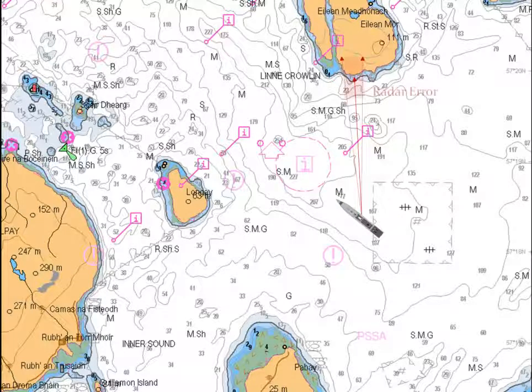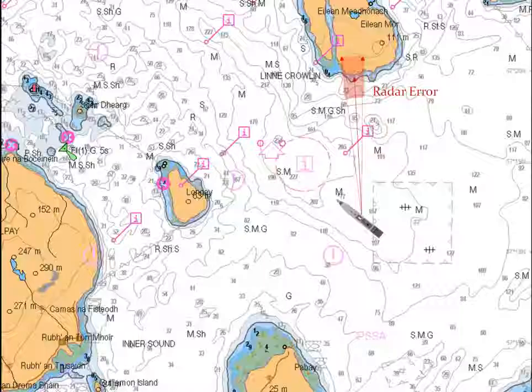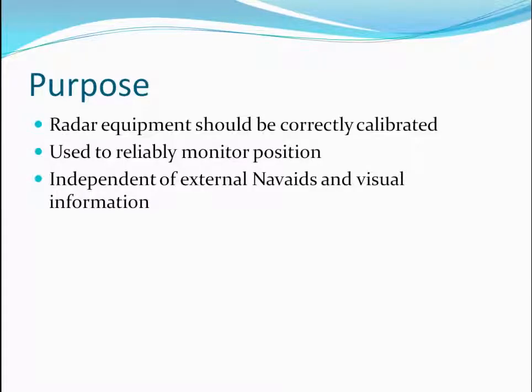When using the ship's own radar, if the system has been correctly checked, the errors are known: the index error along the radar bearing and the rotational bearing error. So with a correctly calibrated and checked radar, a parallel index can provide reliable positional information independent of external sources, and can be used confidently in restricted visibility instead of visual means if the operator is comfortable with its use.